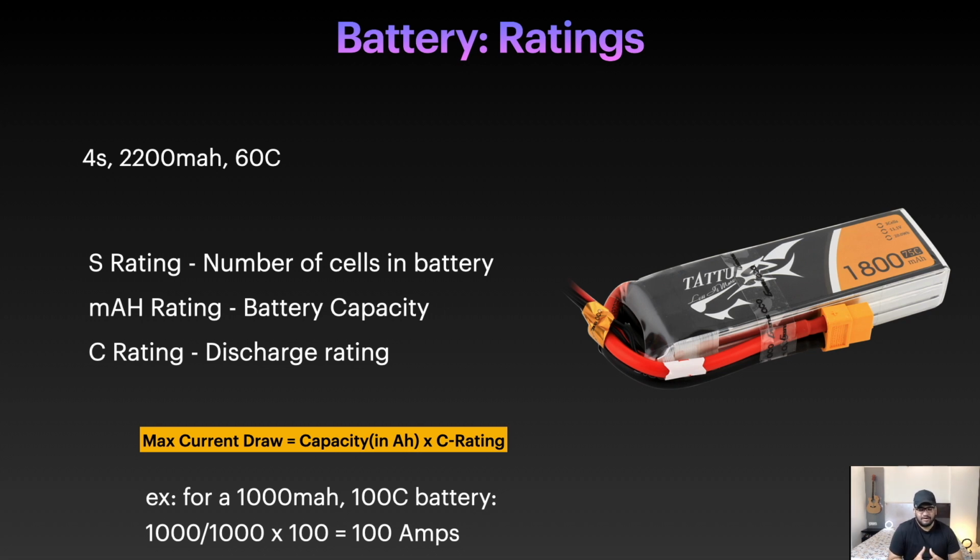It will increase the overall weight of your drone, and it may give you more flight time, but the added weight means less RPM, a less pleasant flight experience, and overall less flight time. So again, finding a sweet spot.